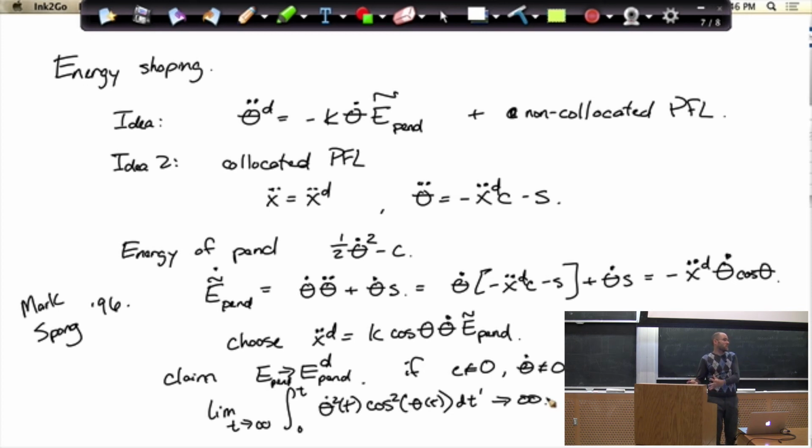It's only for fully actuated robots, but a hugely powerful result from adaptive control. And if you look at the proof, it's going to feel just like this. It's going to feel like I chose a controller so that when I write down the error dynamics between the desired trajectory and the actual trajectory, I get something that is obviously positive times my error, and it goes to 0.